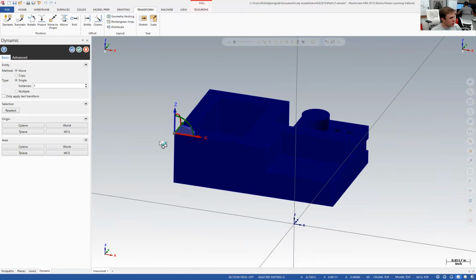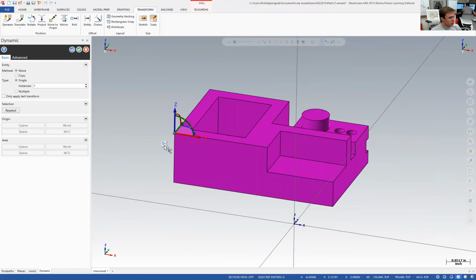Another really important thing to note when you're using the transform tool, and it's extremely handy in applications outside of just moving your part, there's this hidden button that fades out when you're not right next to it. It looks like a couple of shapes right now. What that means is when I do anything on this datum, when I manipulate the handles, it will move the part. Now if I click it once, it changes it to a vector. Now whenever I move the handles, they will move the handles relative to the part, like this.